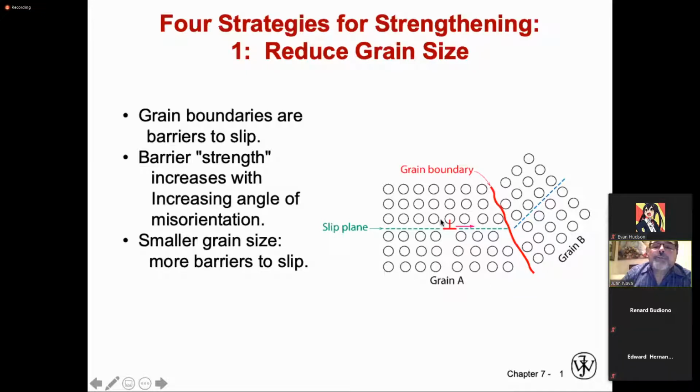The grain boundaries are created at those points where the different grains that are growing in completely different directions come together. That discrepancy between one orientation and the other leads to the formation of the grain boundary. You know that the grain boundary, if there are two interfaces meeting, is a surface defect. The finer the structure is, the more impediment to the movement of the dislocations you are creating.